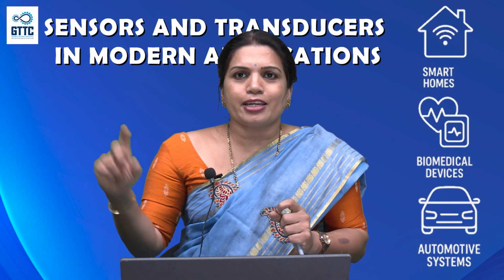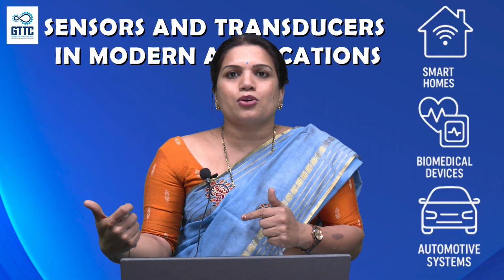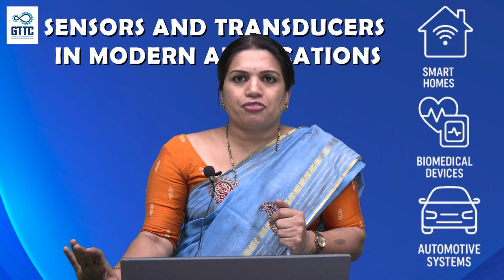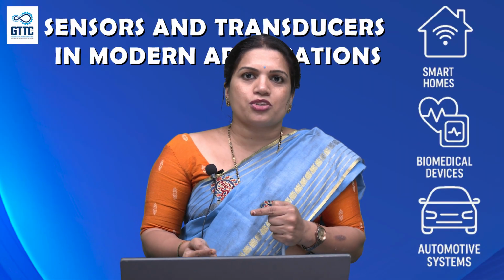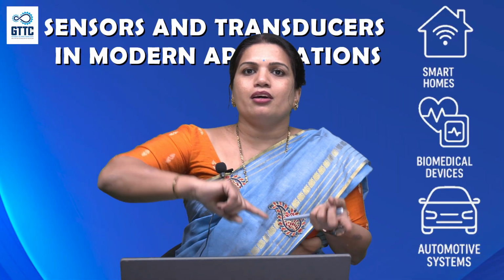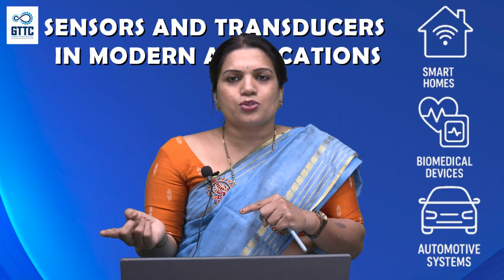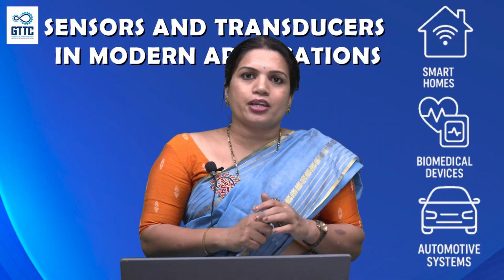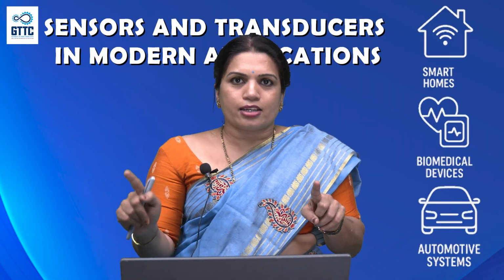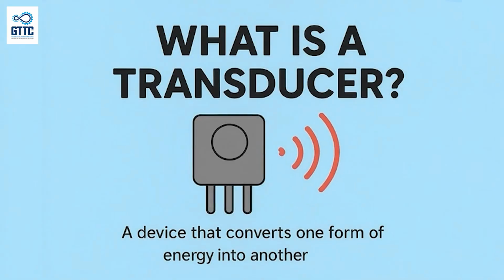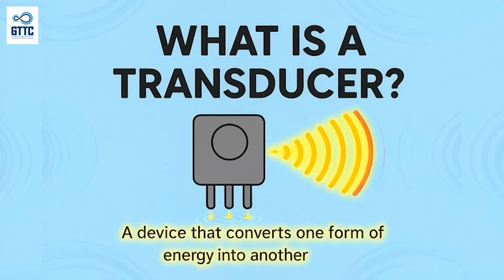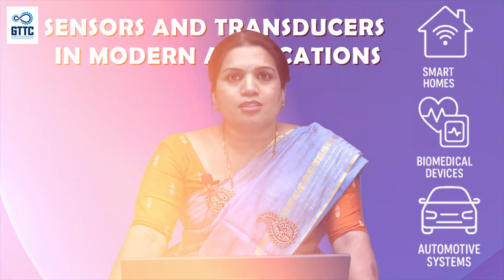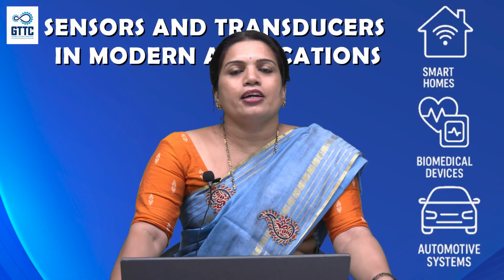Let me come again to the water pump. Now we got the zero signal whenever we have proper soil moisture, so the water pump will be off. So depending upon the soil moisture, the sensor detects it and gives the signal through the processor to the actuators. The entire scenario of IoT works on sensors and actuators. Here, sensors and actuators both are transducers, but sensors work as an input transducer, where it converts temperature or other physical parameters into an electrical signal.